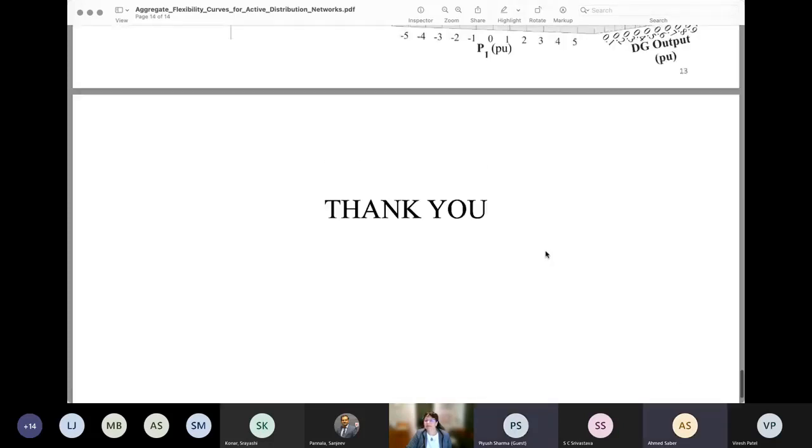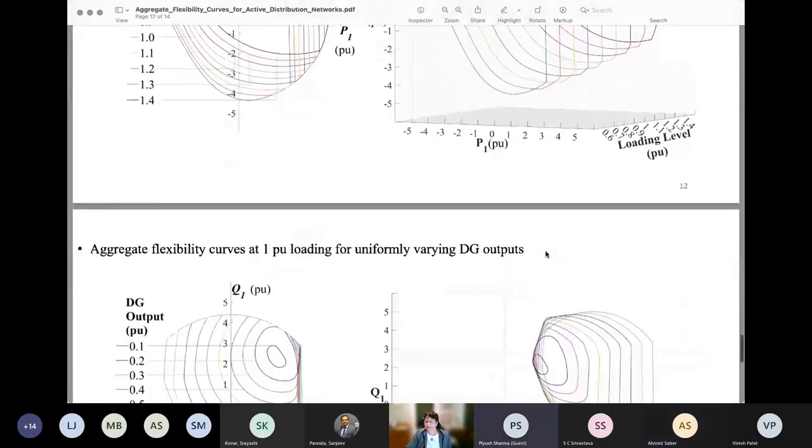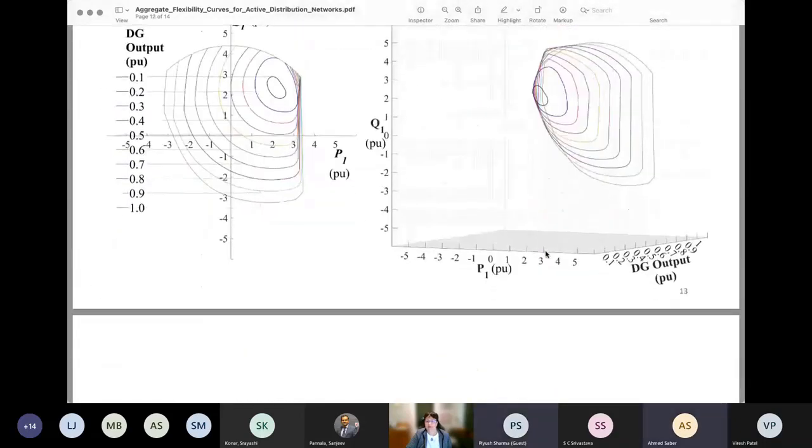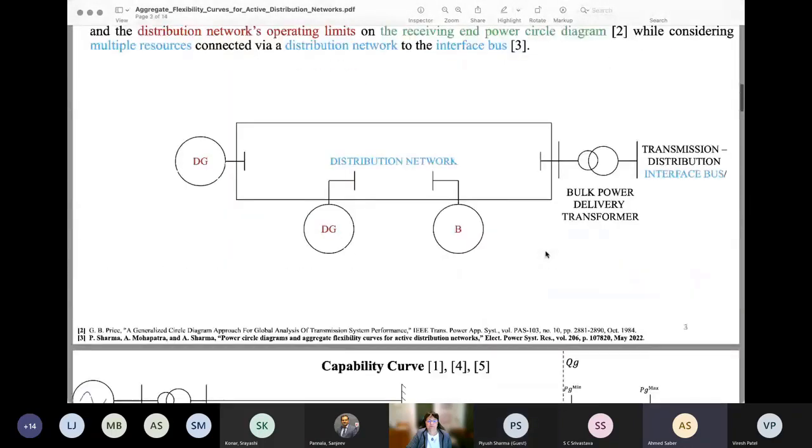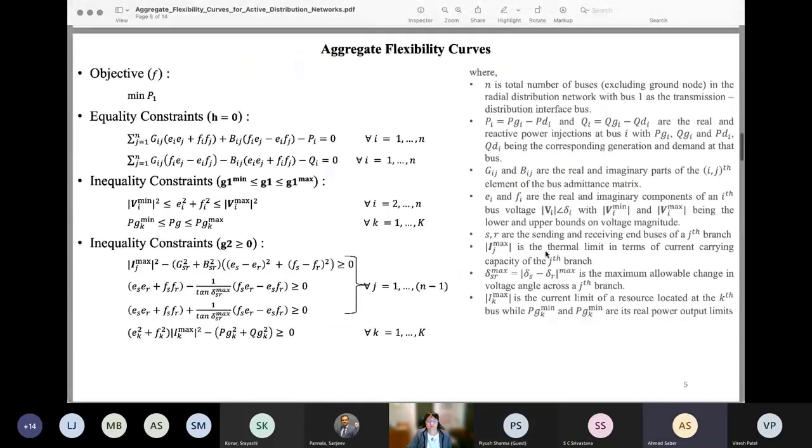Yes, the thermal. Can you please clarify the thermal limit? Yeah, I have seen your optimization equations, and that's a very good thing. But did you also consider thermal limit? It means, let's say, the ampacity of the cable or your transformer limit. Did you use that? I did not see anything.